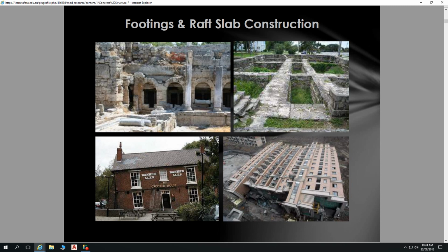And there are certainly ways to go around dealing with those defects and joins and so on. It's the silicon, so your silicon joins and you smooth them off so you get these perfectly flat edges, etc. for various different grades of concrete finish. But we'll need formwork. That formwork also has to be in place. It has to be put in place in a very secure fashion. What we do not want happening is whereby formwork falls over, and then we get concrete pouring out on site.